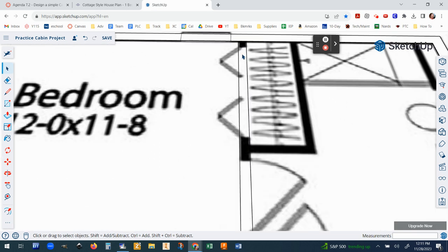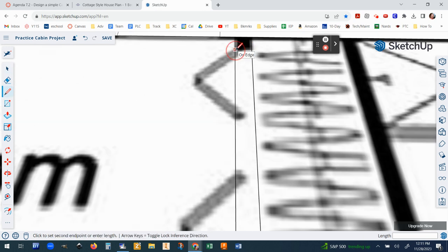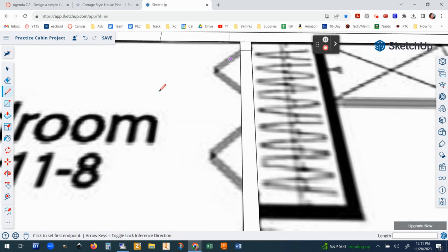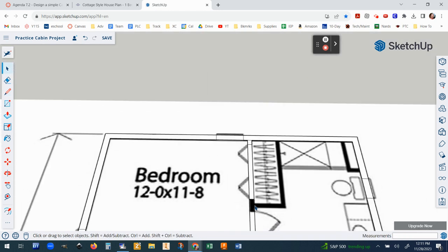Now let's start making our openings along this wall. Okay, so let's start up here. We have an opening starting here and there. Notice I'm keeping it red. Select the wall and delete. If you need to pause the video if I'm going too fast, please do so and go back if you need to. If I'm going too slow, just speed it up.